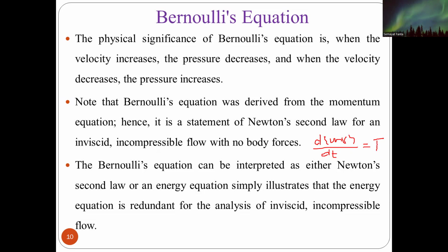Okay, that is Newton's second law. Therefore, for an incompressible inviscid flow with no body force, we consider that Bernoulli's equation can be interpreted as either Newton's second law or the energy equation. So it can be interpreted in different manners. From this momentum conservation we find Bernoulli's equation, and in the same way we can find it from energy conservation.